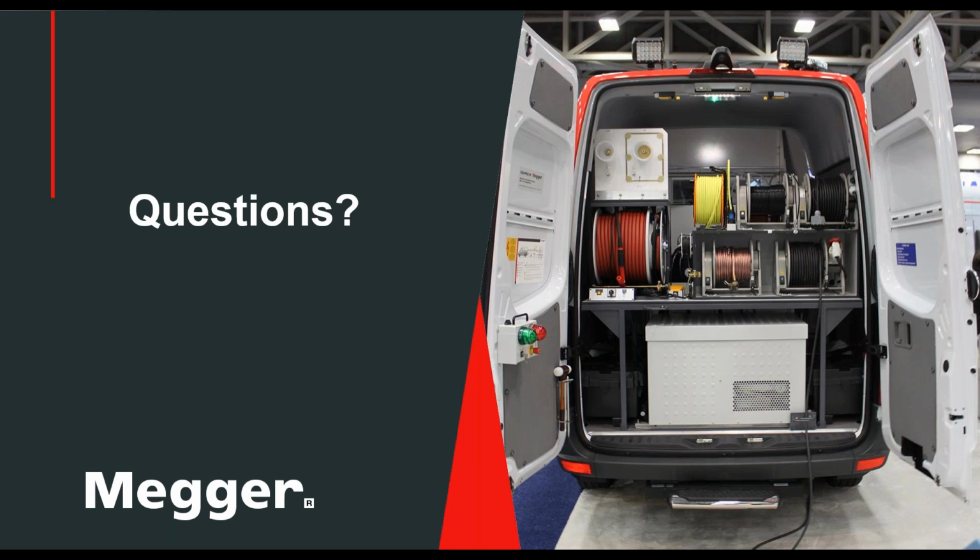You have 2 faults, 2 paths to ground. When you start to apply high voltage, in general terms, that voltage is going to seek the path of least resistance to ground. So what happens when you have 2 faults, assuming that they have different resistances, is you'll find the lowest resistance fault first.